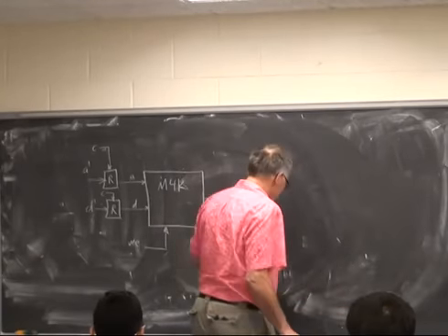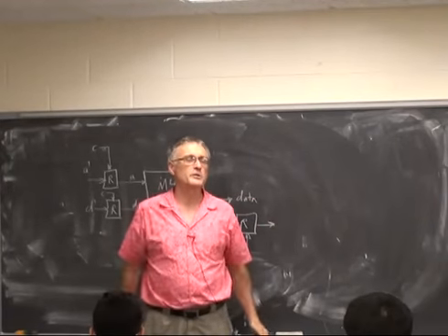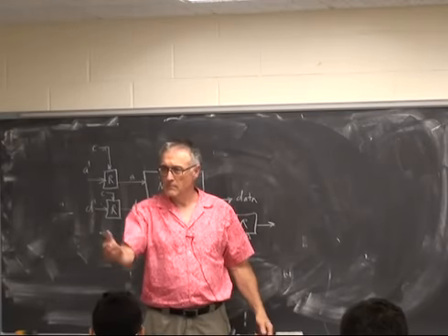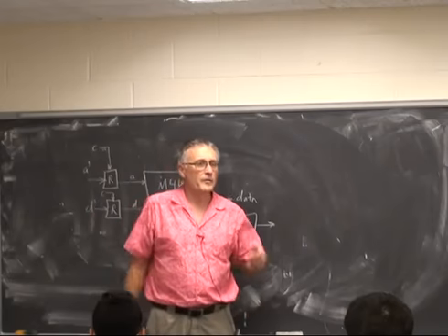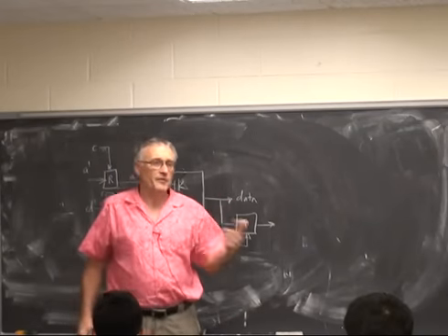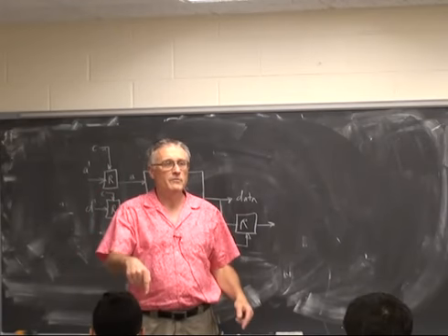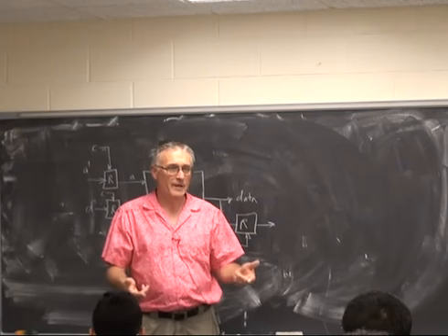So then what you're asking is, how do you randomize the seed for the random number generator? Any ideas? Perfect. Right. So if you have the seed changing at 50 megahertz, then the time you push the button relative to the seed is essentially a random value.